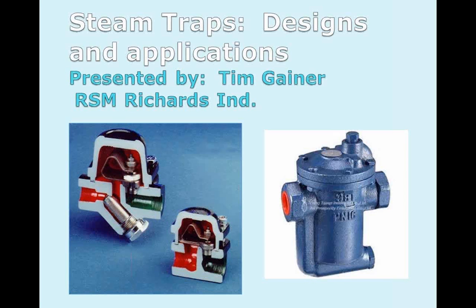Okay. The next question we have is, we found that some inverted bucket traps do not have the small orifice. Why? And what happens if the orifice is closed? I don't completely understand. Most of the ones I'm familiar with have that orifice, actually. I've not run into one that didn't have it. I can only make the assumption that with that particular model, they're just letting the steam condense within the bucket.